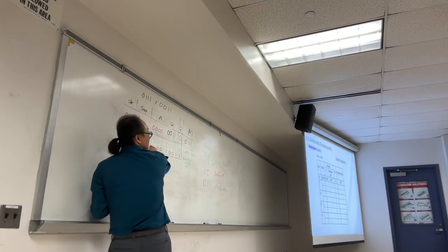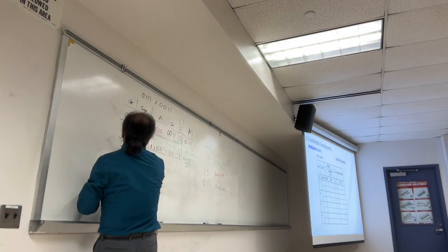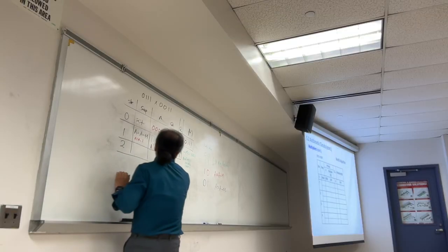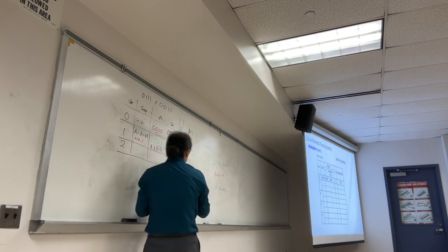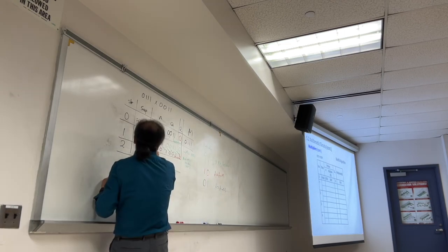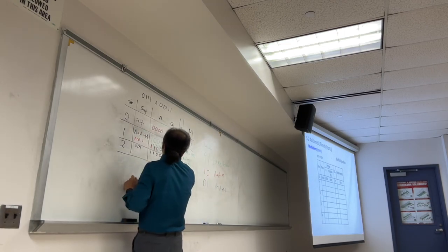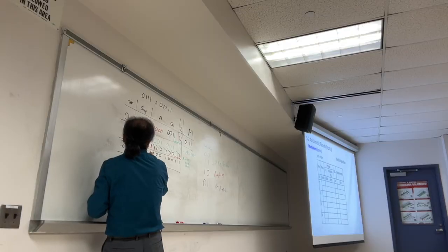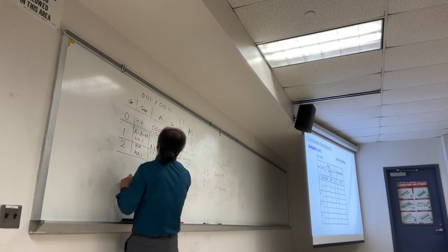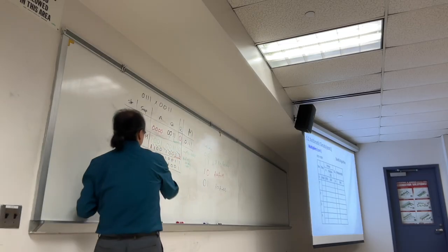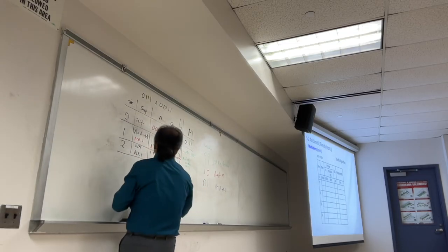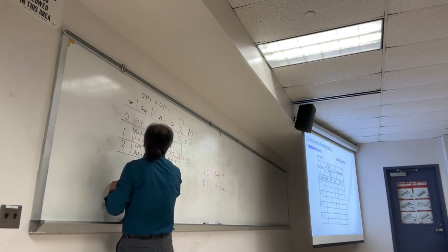What do we need to fill in here? 1. And then iteration 2, we need to look at the lower 2 bits, 1 and 1. They are the same. No action. Yay. Let's copy down. Arithmetic shift to the right by 1. 1, 1, 0, 0, 1, 0, 0, 1. And we need to fill in 1 again because it's a negative number.